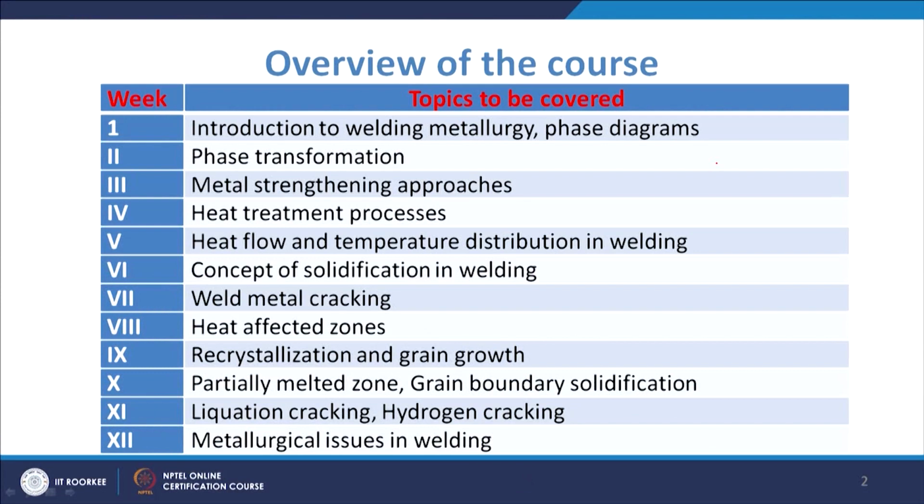In phase transformation we are going to talk especially about the solidification aspects and how the different types of heat treatments are applied. We are going to talk about the CCT or TTT curves: how the different phases are transformed, and how they differ when you have different types of treatments given, different types of heating or cooling, and how they will give you different phases. That will be under phase transformation.